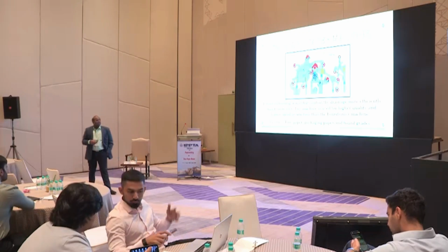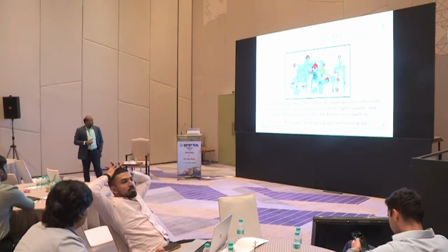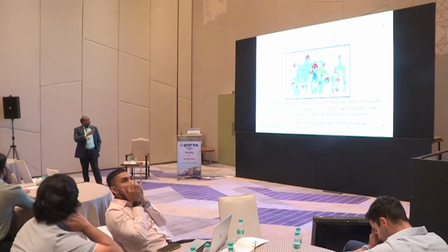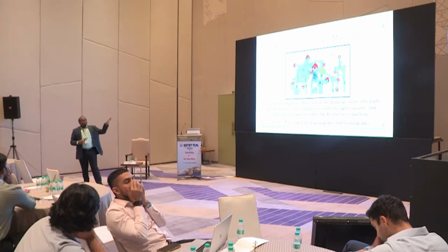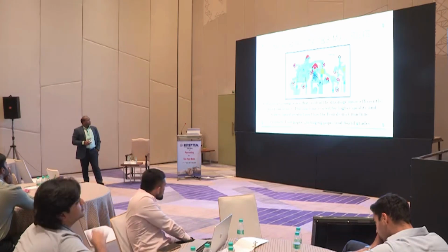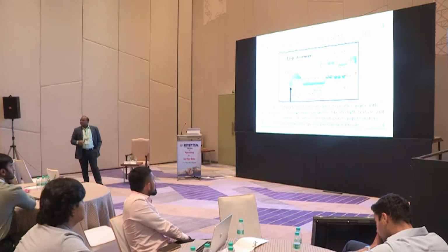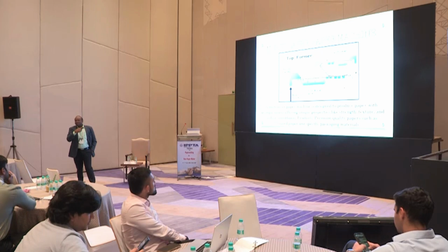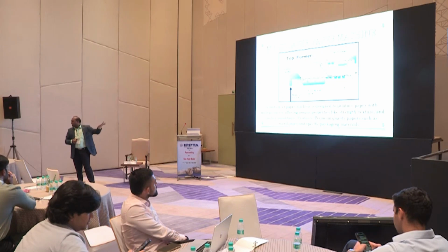And this is the twin wire part paper machine. It has two forming sections, as we discussed. From the view, it looks like this only. And the top wire former, multi-layer former, someone asked about that. Yes, sir. This is the multi-layer former, where the top wire will be on top of the Fourdrinier wire along with the head box. This is not the hybrid former.